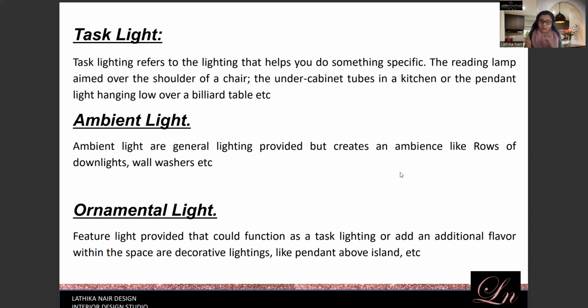So it's the same light, but when it's used differently, if it's used under the bench where you're working, LED strips, they will be termed as task light. Say, for example, you've got strips running on your general lighting, which is instead of one down light, you've got just general LED strips running. Then they act as your ambient light. So the same LED strips act as three different lighting: task lighting, general lighting, and ornament lighting, highlighting your island bench. Yeah, so that's right.